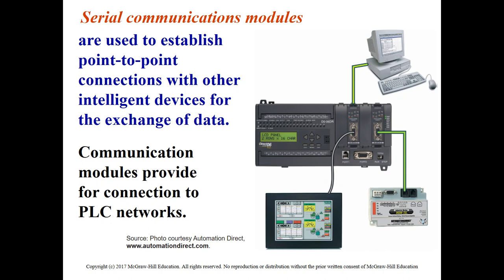So usually the communication modules provide for connection to the PLC network. I mean, if we have multiple PLC systems, like we want to control multiple processes, each process has its own local PLC system. So we want to connect the different PLC networks here. We can use such serial communication modules.